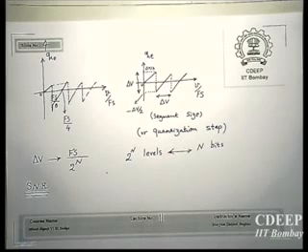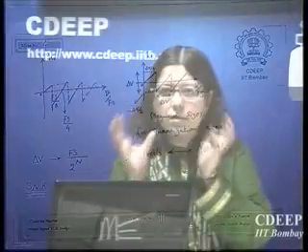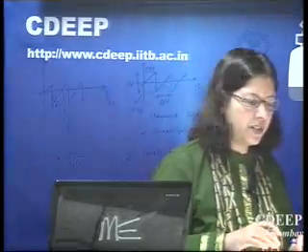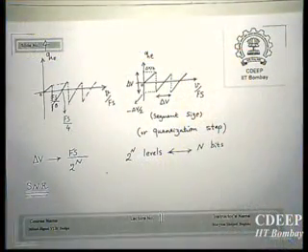We could call it signal to error ratio, that is also correct, but in literature it is called signal to noise ratio because afterwards other sources of noise and quantization error are clubbed into one complete noise source. But of course they are not of the same nature. For example, thermal noise is random noise, but quantization noise is not always random.